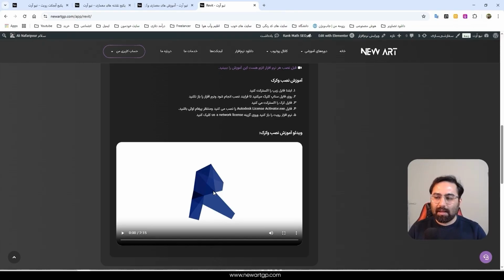Let me also tell you that there's absolutely no problem with having multiple versions of Revit installed. It's totally fine. And actually, by its very nature, Revit fundamentally doesn't allow you to open project files from a newer software version in an older, previously released one. But overall, just so you are fully aware and completely understand, a file that was originally created in the year 2025 absolutely cannot be opened in the earlier version of 2024. A file that's worked on in 2024 also can't be opened in 2023. It can only be opened in its own version and in higher versions.